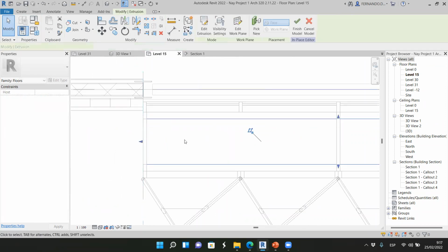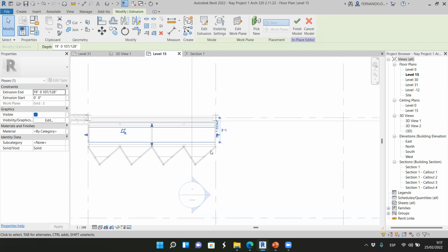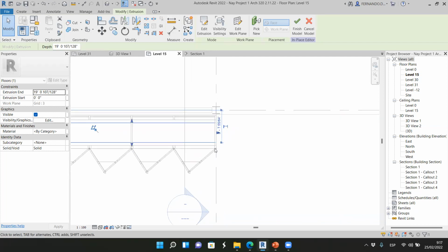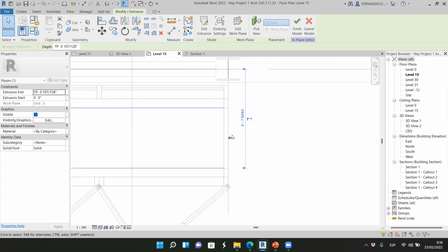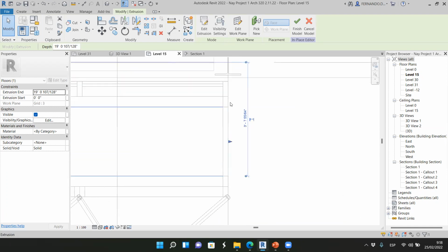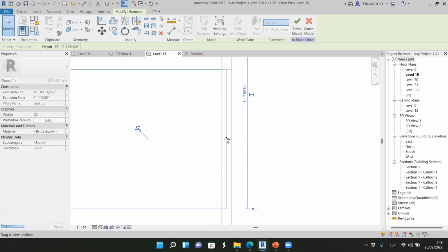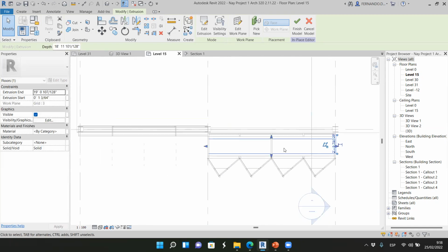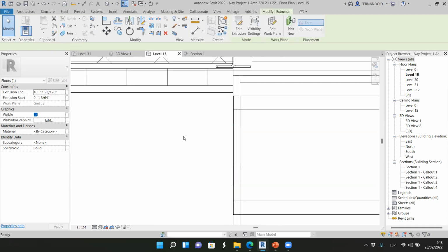And this has to be continuous through the, if you have another curtain wall like this here, you have to copy all what we are doing. So this has to be aligned with the midpoint of this element. So let's drag it to the midpoint, kind of. And this one here. And then finish the model.